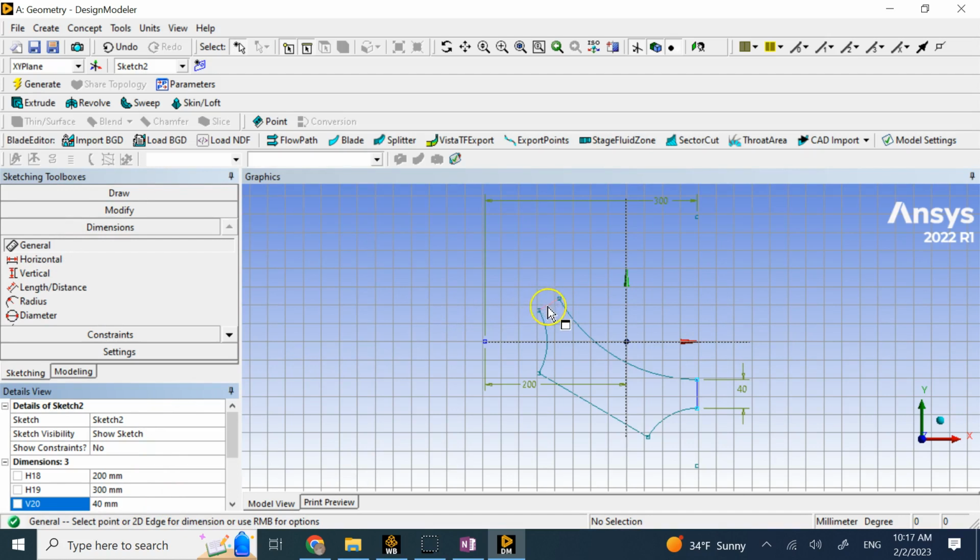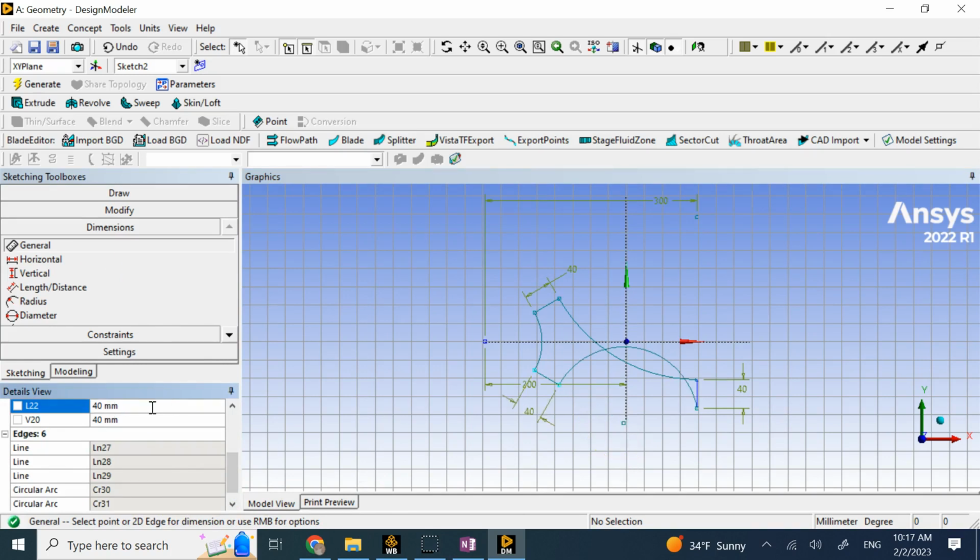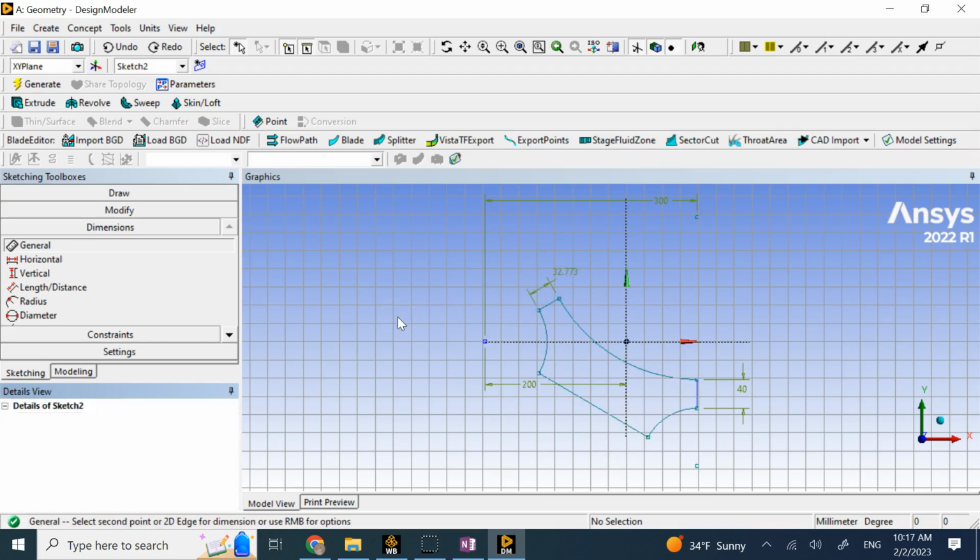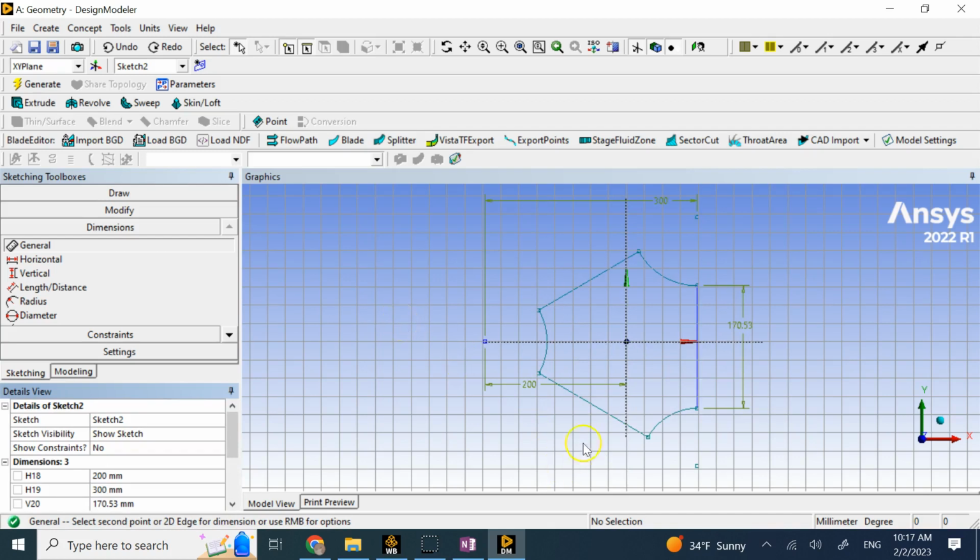Then we'll try to do a similar thing to the other ones, or we can use the equal again. So it is up to us to choose how you want to define it. Now, the problem is this. You see, the way that I did this, it is completely ruining your sketch. So the order sometimes might be important, and the other thing is symmetry also, because when I deleted those corners, some of the symmetries are gone.